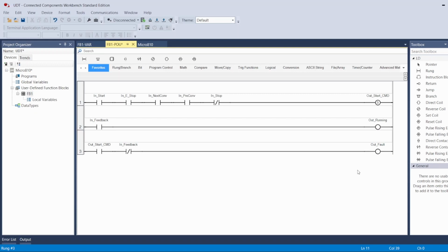But at the same time, I know that the motor sometimes doesn't start right away, or it doesn't get to high speed right away. So it depends on your feedback system. If it's an encoder, you might be able to see it turning right away, changing positions. But if it's a proxy, for example, monitoring a full rotation of the motor, this proxy might not see the motor is running until the motor goes through a full cycle, a full rotation. So the motor maybe needs a few seconds, whatever. It needs time before it shows you the feedback.